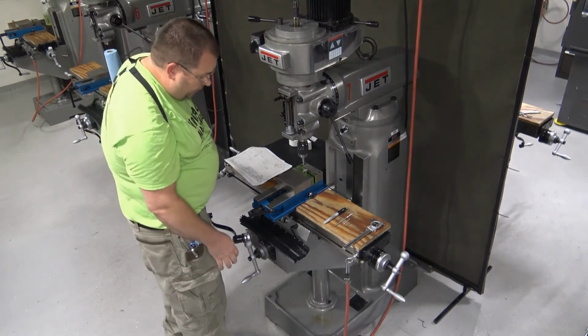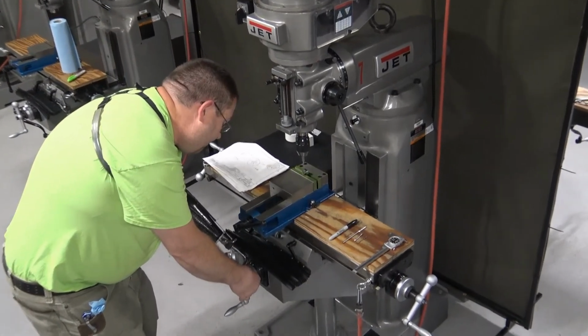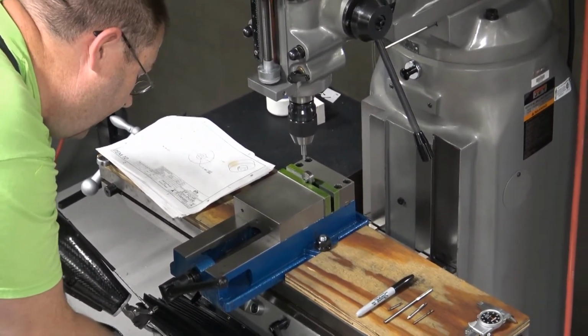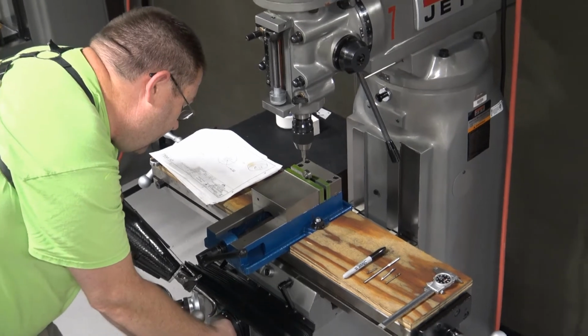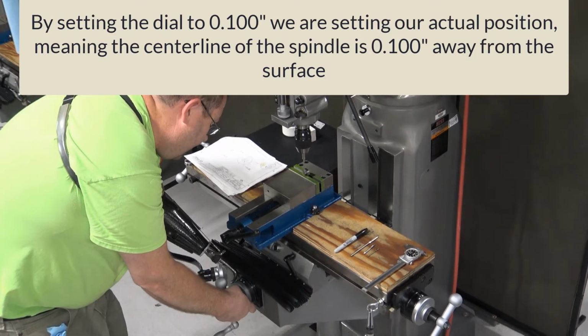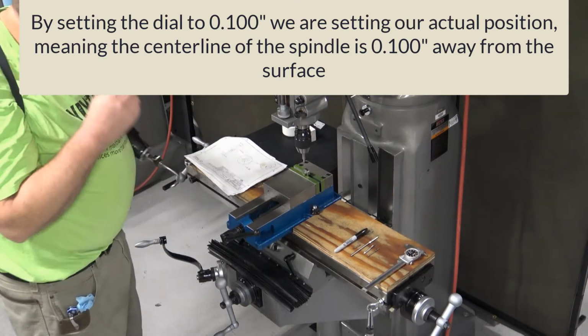Now that we've edge found the front, before we move the machine, I'd like to take a second to reset my 0. Now, I set my 0 to 100 thousandths because that's how far away from that face we actually are.